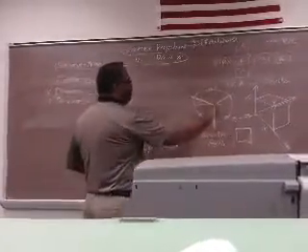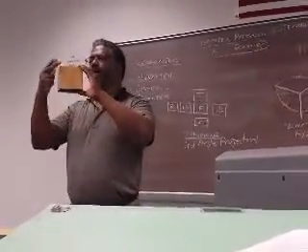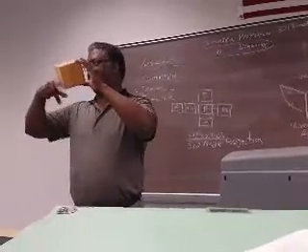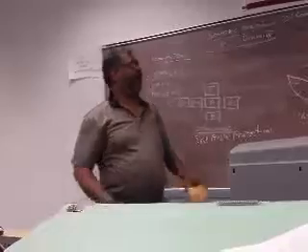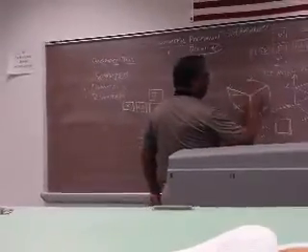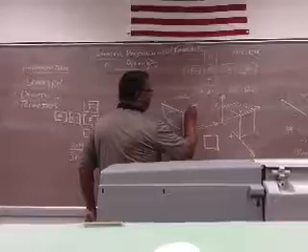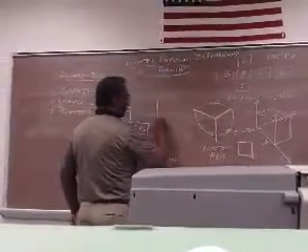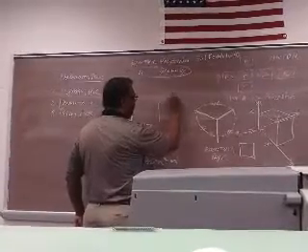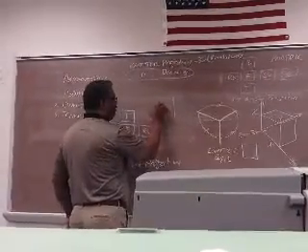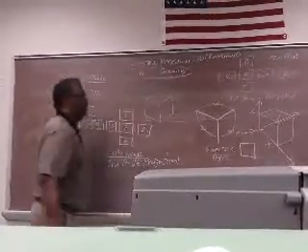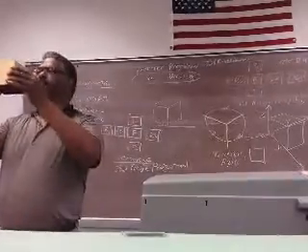So this is the edge here that you pick up when you rotate him, and then when you rotate him along your next axis, these lines appear to be going up at an angle. Well, depending on the rotation, that angle becomes 30 degrees, like that. So when I'm looking at this object here, that's my corner of it. This is a 30-degree angle, and then he's coming up 30 degrees, and then I get this isometric cube right there, based on this rotation.